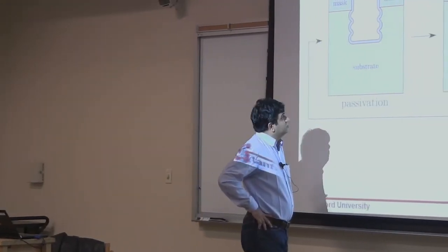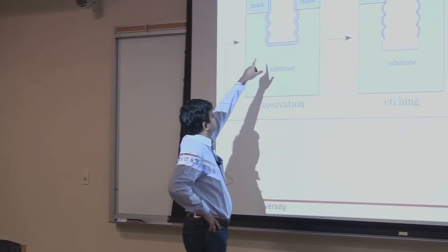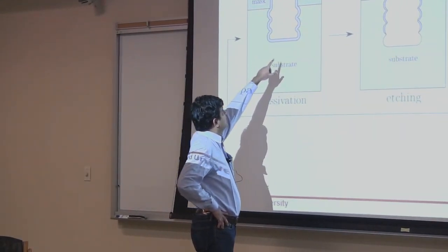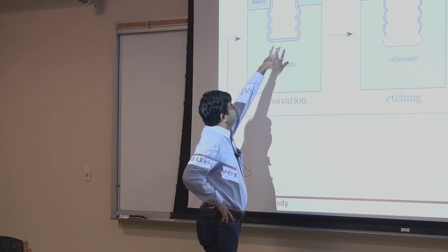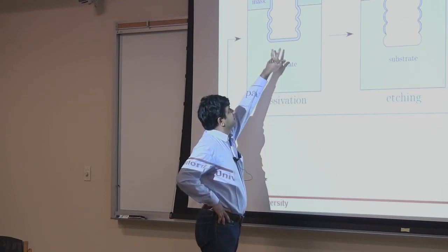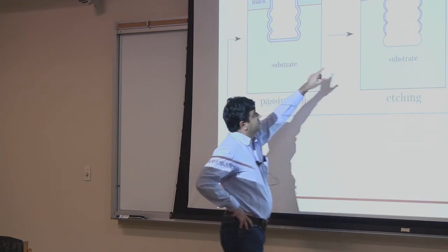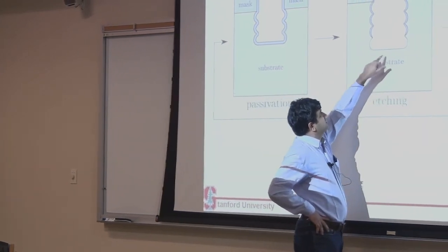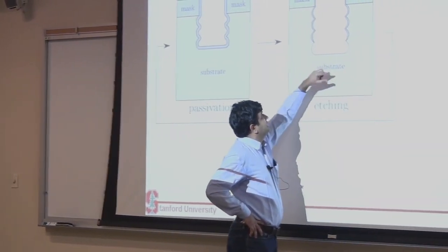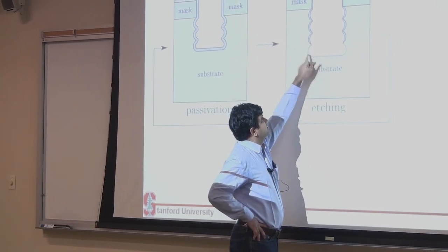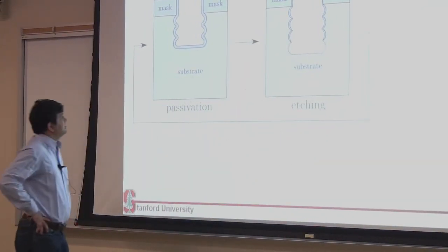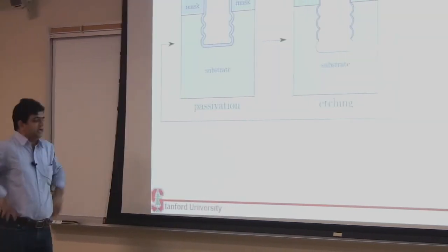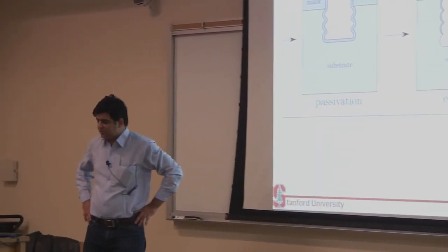You have this passivation layer which comes from your etch residue. Then you do a RIE step, so it's a very vertical step, you remove it. And then you etch it slightly deeper, so it causes this barrel. And then you enable that plasma again, so you passivate it again. So it's a cyclic process which is used to etch this high aspect ratio structure.